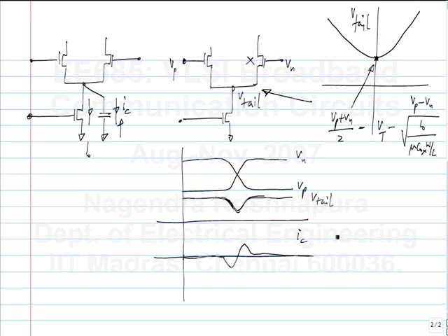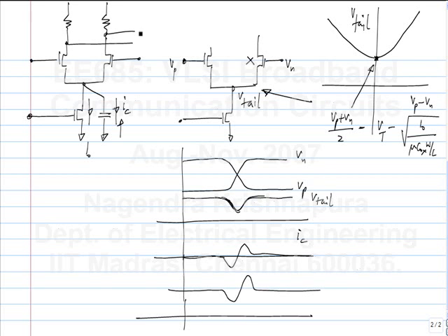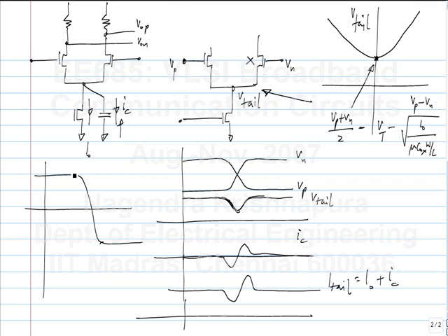So what does this mean? So the tail current will be this plus the constant current I0. So the tail current also does something like this. What will it do to the waveforms at the output? In response to this Vp minus Vn, I should get a Vop minus Von, which is, let's say, like this. What will I get in presence of the capacitor? When it starts falling, there will be an increase and then something like this.